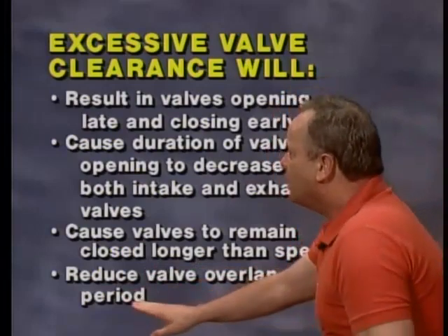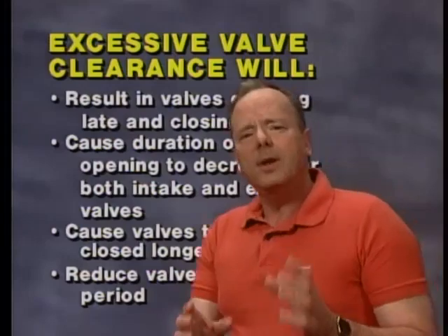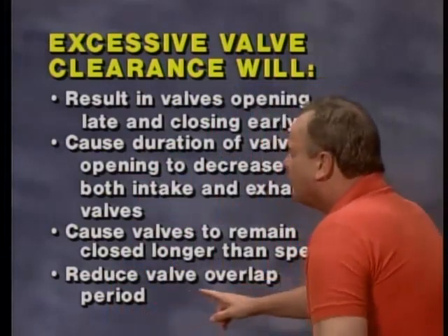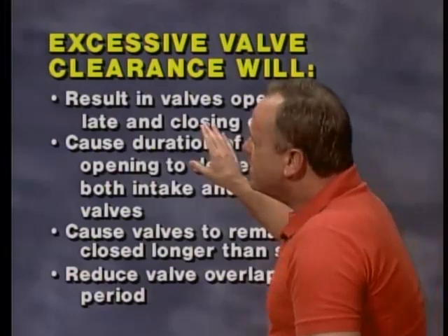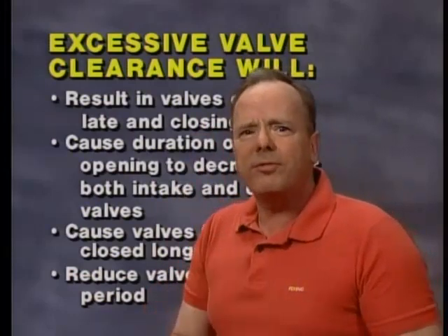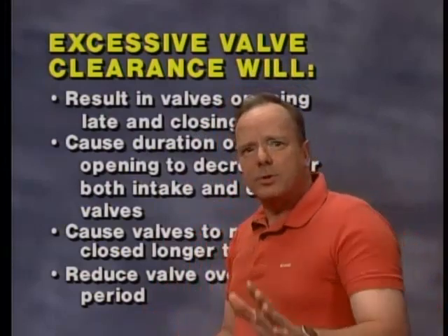And it's going to reduce the overlap period, because the overlap period is that period during which both valves are open. And if they're going to be open less, it's going to reduce the valve overlap period. So excessive clearance in the valves is a bad thing. There's too much play there, and they're not going to be open enough, and they're going to be closed too long. And that's what you need to know about it.